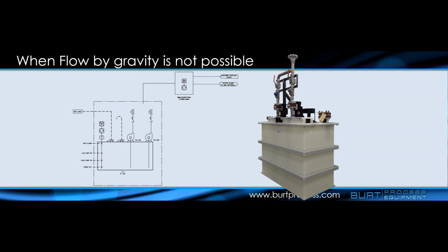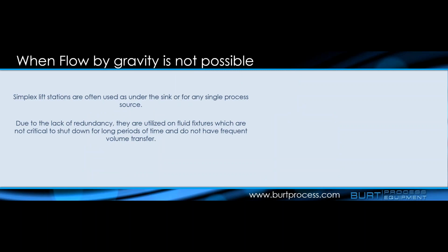And you also have laboratories in that area that you need to actually put to your waste stream. It's tough. It's doable to put a pH system in a pit or some kind of a lower level than that, but oftentimes it's just easier to put in a lift station or a transfer station in those cases, like something like the one shown here.